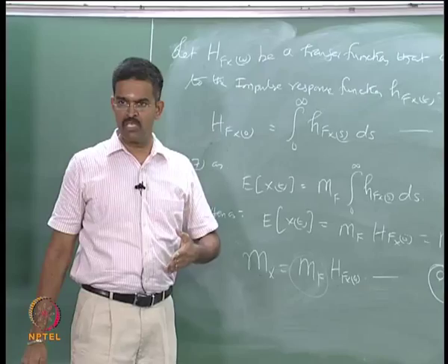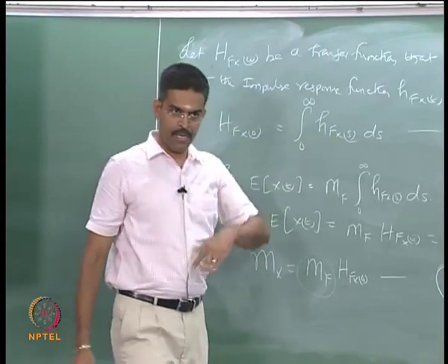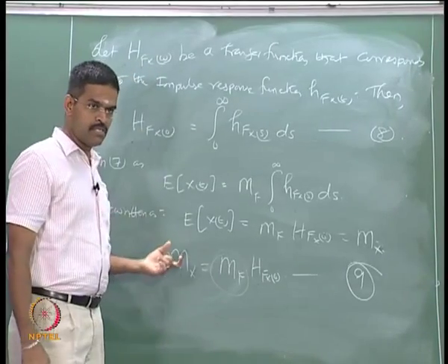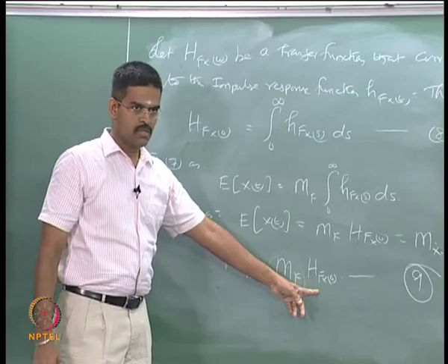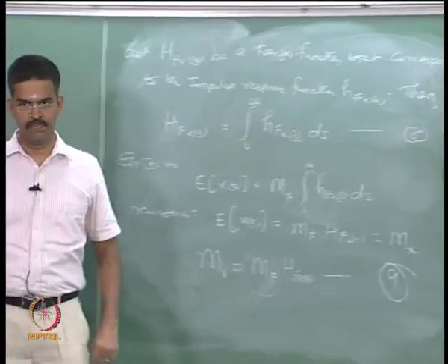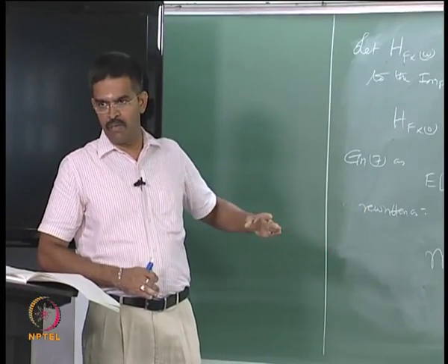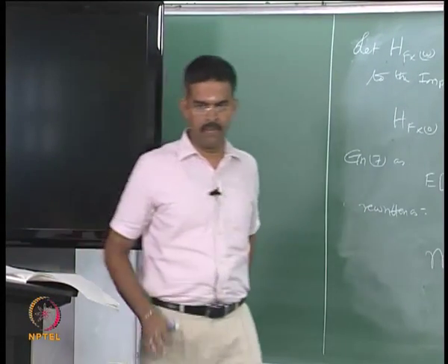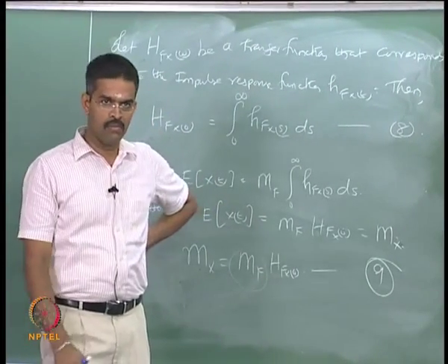In a stochastic process we will not get the absolute values of x, we will get only the statistical parameters of x like mean, standard deviation and coefficient of variation. So I can get this if I know this. My objective is, for a given problem, how to get this value. Agreed? And there is no time dependency here, therefore the process is completely stationary. Now we will take up a single degree of freedom system example.